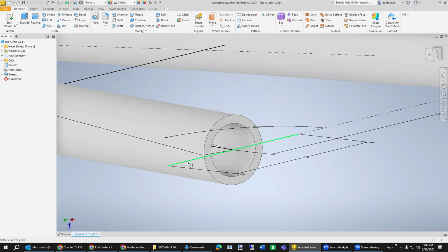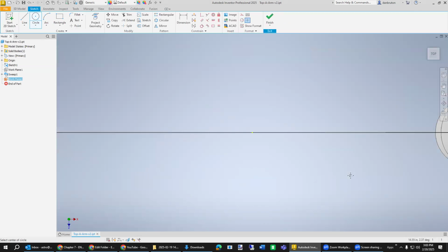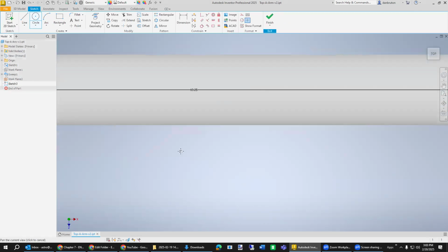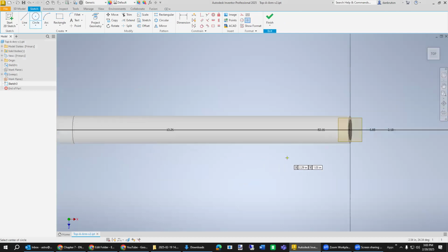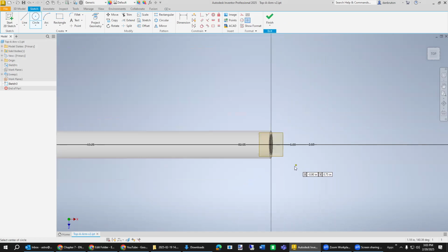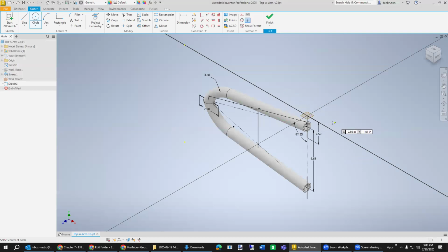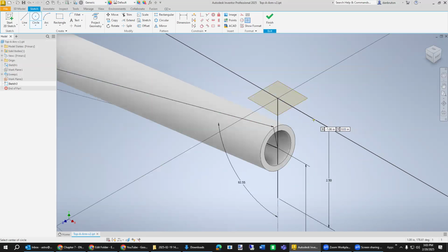So see what I did wrong this time. Maybe I'll do both steps at the same time. So I select the curve and the point to create the plane. And then I'm going to draw a circle on that shape right there. And yeah, that's where it seems to be an issue where it's not letting me look at the part that I want to draw on. Now it looks like it's possible to do it.